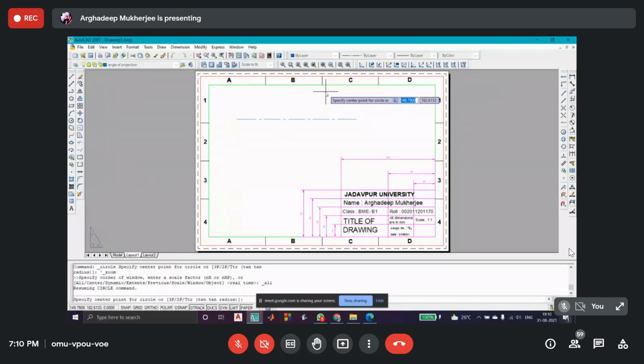When you do the drawing, also try to give names to different layers as I have given. I have used a second layer here for the center lines, the lines of symmetry. The color of the line of symmetry will be changed so as to show that the two layers are different, right? The layer name is center and the color is something different, not black. But the continuous line color is black or white. Now there are two layers, right?